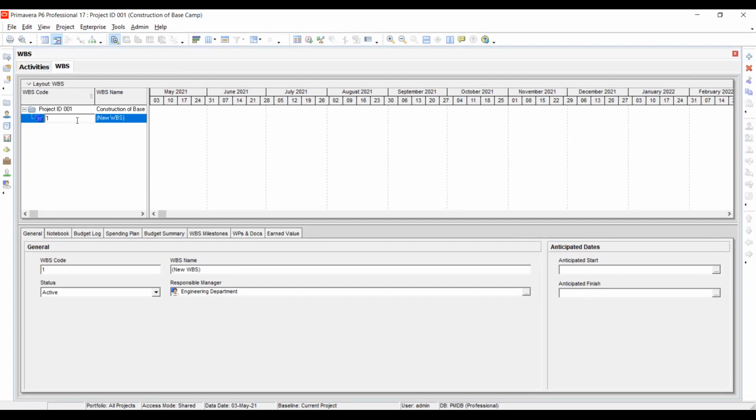So these are different levels on a work breakdown structure. If you go to level 1, for example, the one that has preliminaries, substructure and superstructure, it can have numbers like 1, 2, 3. But when something falls under substructure, it will be like 1.1, 1.2, 1.3.